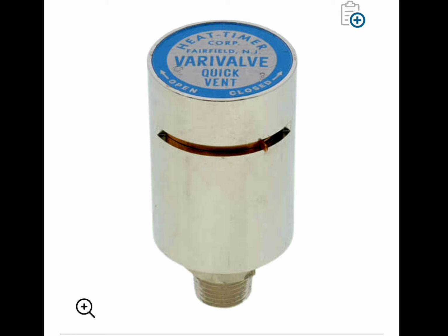If you have to use this particular vent, I would recommend using it at the top of risers, and I would recommend angling the opening of the vent away from the public, because these things have the tendency to spit out scalding hot water that could get right on you. So it's best that you don't have it facing toward the public. However, can you get away with using these on self-standing cast iron radiators? Yes, you can. Are they the best when it comes down to venting them? No, they're not. But you still can use it, just based off of the construction of the radiator and the fact that cast iron radiators hold their heat better.